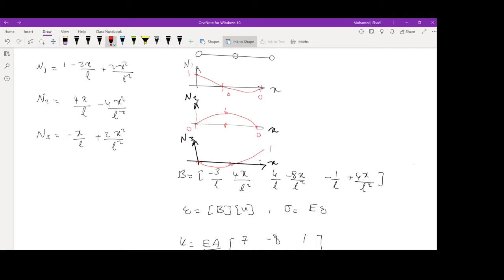So it is 1 here and 0 everywhere else. Just use the dashed line here. Now you can multiply just like what we said for the first element, for the linear elements. You can multiply. Oops, this is too thick. This is the one. So you can multiply the first shape function with u1, the second shape function with u2, and the last shape function with u3, and combined you can produce any displacement field.